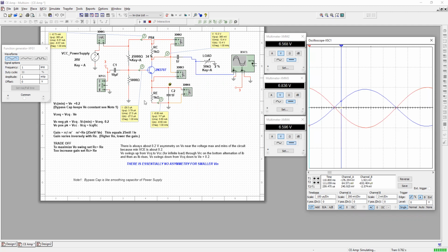This is ICQ, and it's going to set a voltage at the emitter resistor and the collector resistor. This input, passed through to the voltage divider stage, is going to increase and decrease my base current. As the base current rises, the collector current also rises, and the voltages around the collector and the emitter will increase.